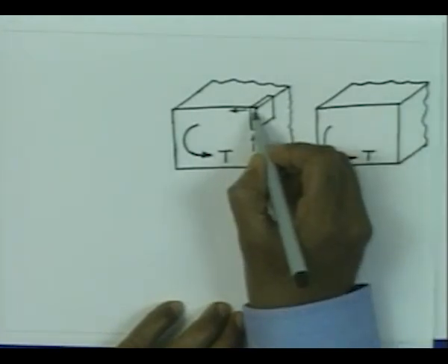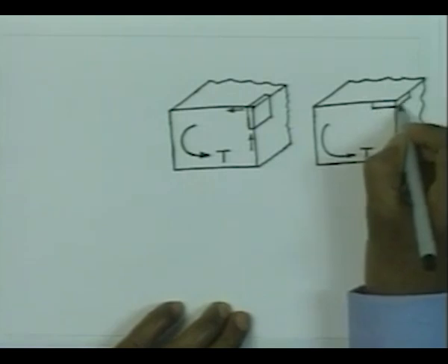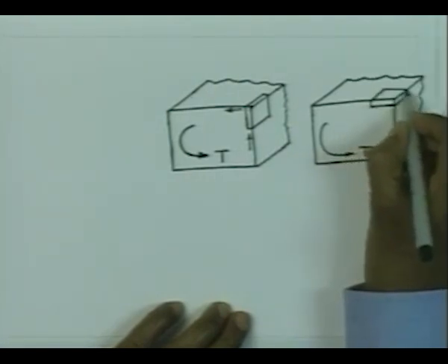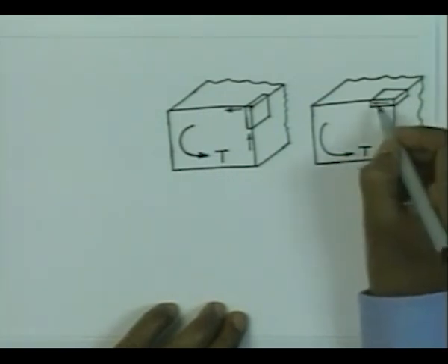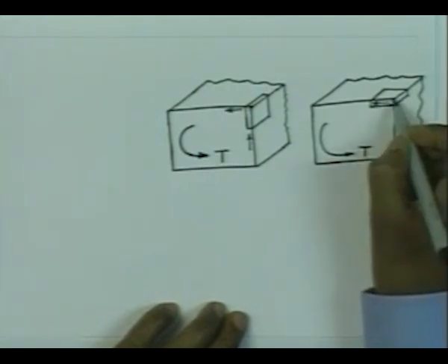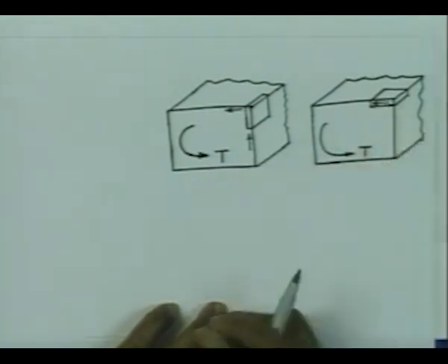Similarly, if you now consider the stress, let us draw the element for clarity. So, let us say that this is the element. If the stress is going to act at this point parallel to this boundary, it has got to be directed like this. Now, this stress is obtainable from the slope of the phi surface in the perpendicular direction. Since phi is 0 along this boundary, again the slope is 0, therefore, this stress is 0. So, this is from Prandtl's membrane analogy. So, you can find the answer that the corner stress is 0 from the uniqueness of the stress at the corner point and from the membrane analogy.